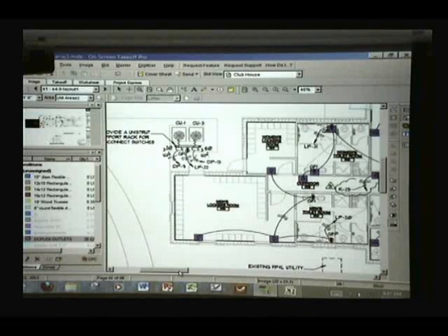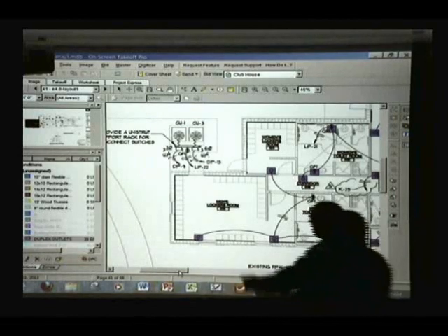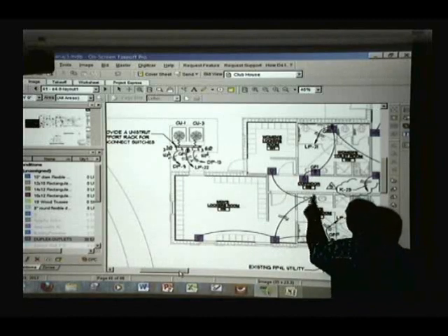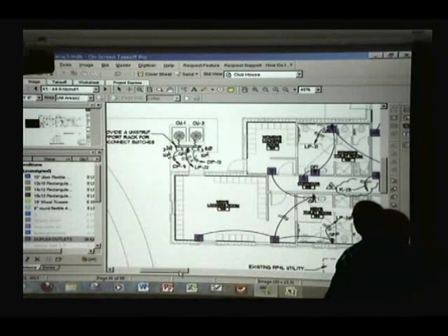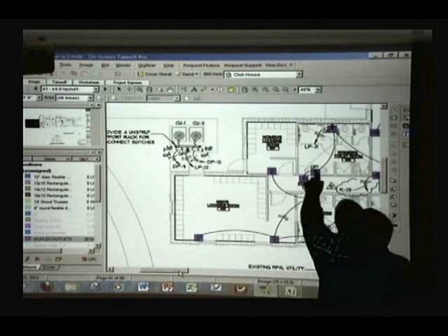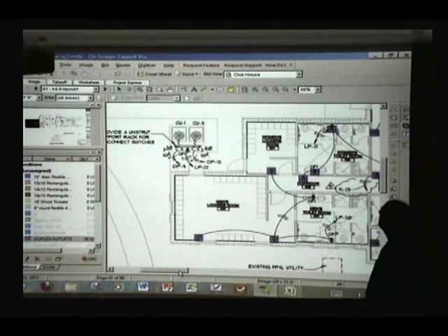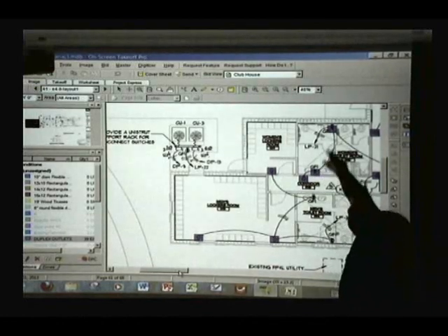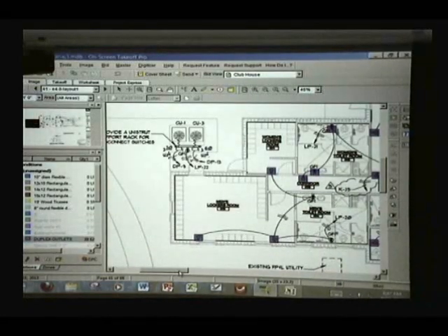So see, this is what I mean. They are connected electrically, so you can follow these cables and see where they end. So this here's a GFI. This one protects that loop, and here's another one. So I'm going to account for the GFI separate. I'm just going to account for these doubles. But see, the auto count also, I got some GFIs here. Maybe I shouldn't have selected them.